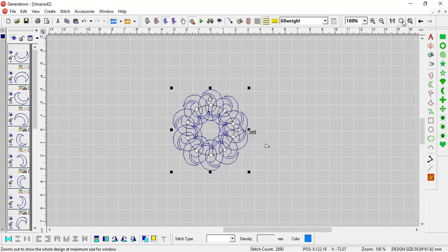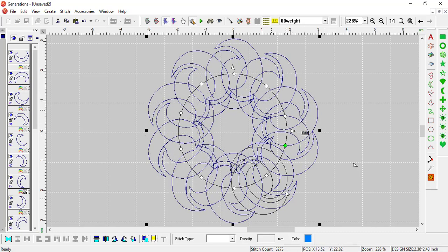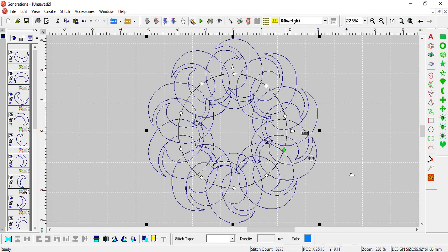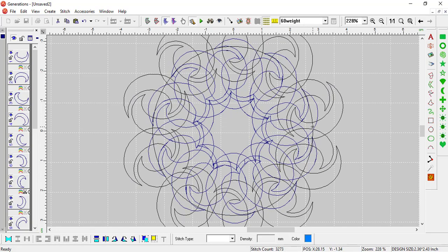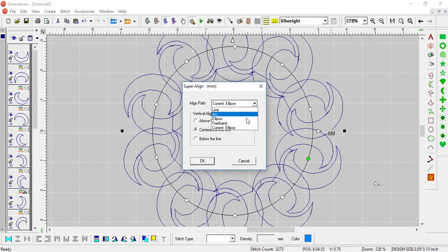And let's go ahead and zoom the whole object. And I will regenerate, because I do want to regenerate my design. So here you can see we can take each individual one, left click, hold, and drag, bring it around, change the different settings. We can also hit Edit and change the text path if we want. So let's say I wanted to put it on an arc.